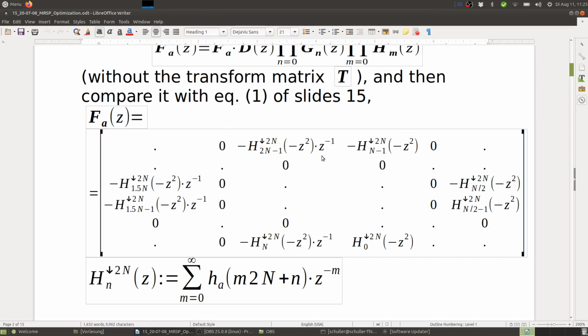So if we have a polynomial, then we know that the polynomial in this place is this polyphase component of our baseband prototype. It's the downsampled baseband prototype, downsampled by a factor of 2N, given these phase shifts here, 2n-1 or n-1, and with all those changing signs for every second polyphase coefficient.